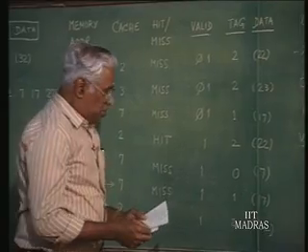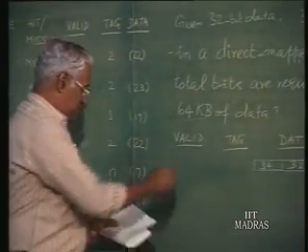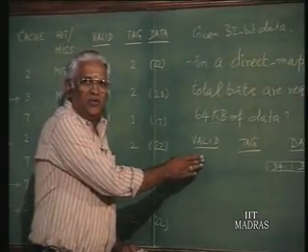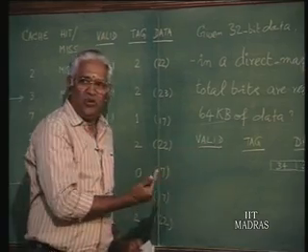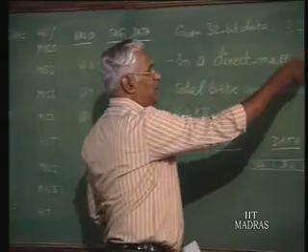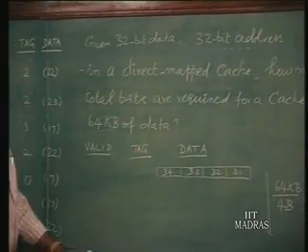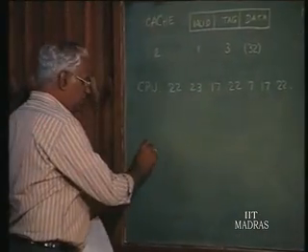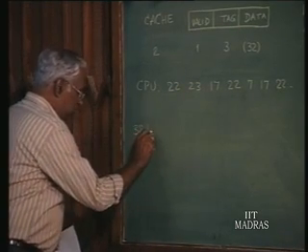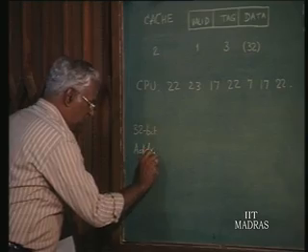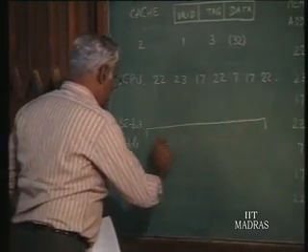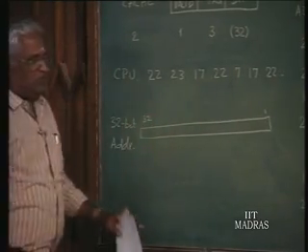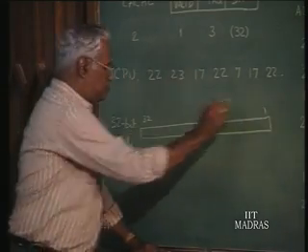Good. Now, let us take the address and work out the other things. The valid bit we do not have to discuss much, because if the data is valid, it is going to be 1, otherwise it is going to be 0. So, the valid field size is only 1 bit. Now, the tag is what we have to work out from the address generated, the 32 bit address size. Suppose I have this 32 bit address, starting from bit 1 to bit 32.